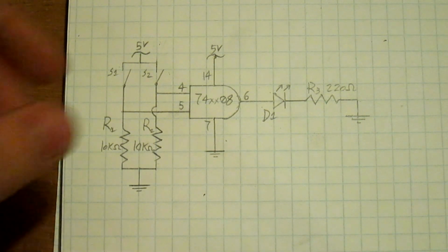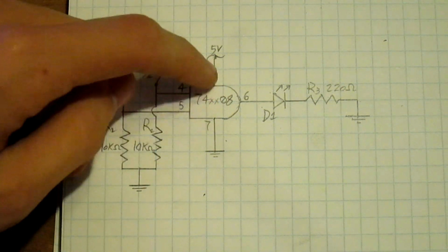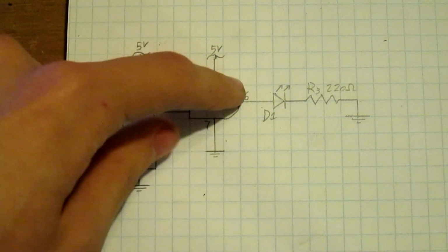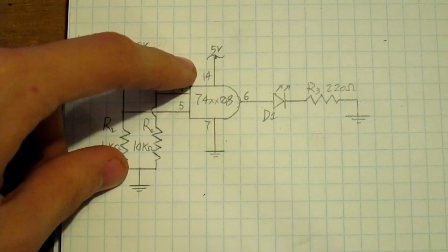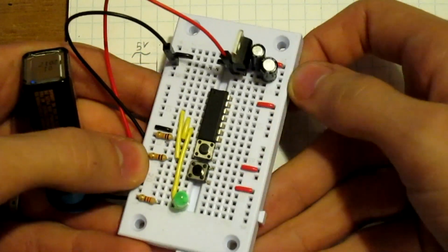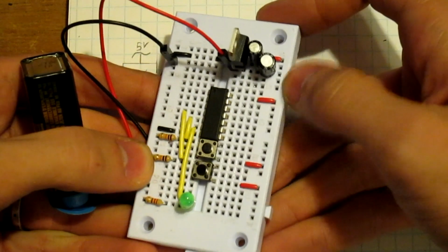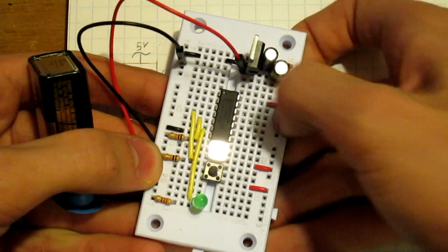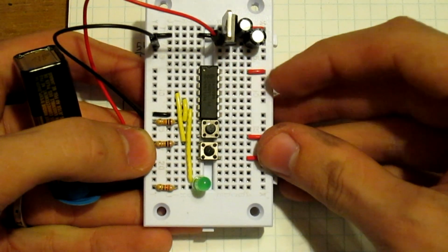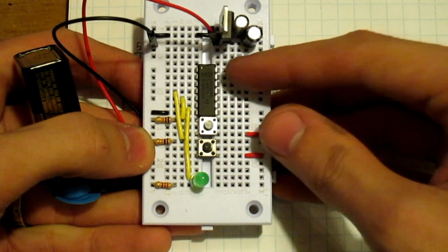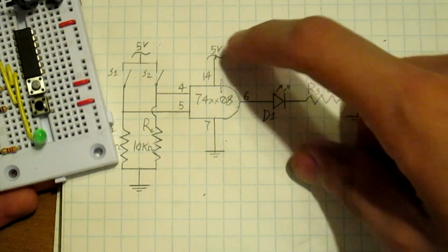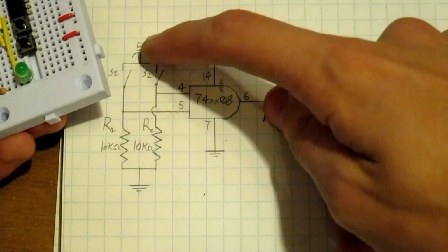So that's that part. And you can see it's got these lines that go up to this thing called 5V. That's the 5 volt thing. On the other circuit, that means you hook it up to 5 volts, and you get 5 volts out of the other circuit. All the 5 volt connections are along this little thing called a bus, and all of these red wires are connected together, and that's 5 volts right there. And this is the integrated circuit that's got the AND gate in it, and it's got a wire going from the 5 volt line to that pin. That pin is 14. As you can see, 14 is connected to 5 volts. So that's all good. And they got 5 volts over here, 5 volts here.